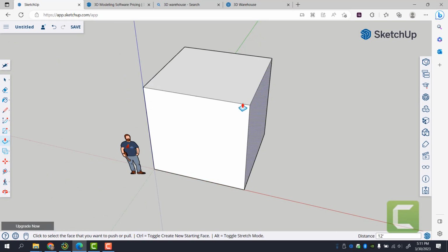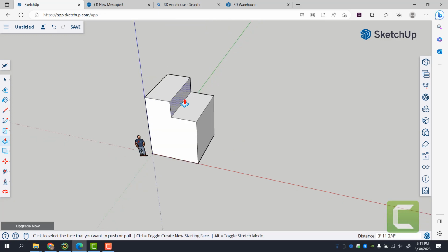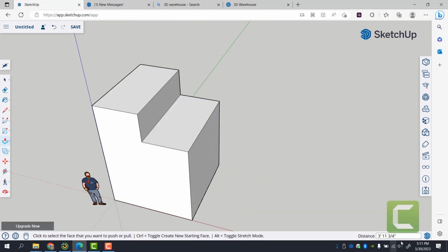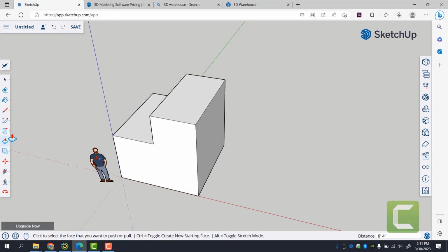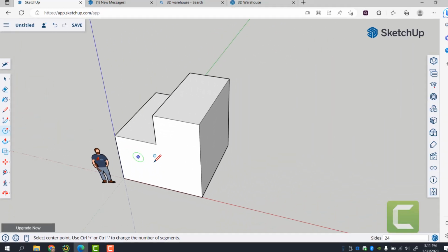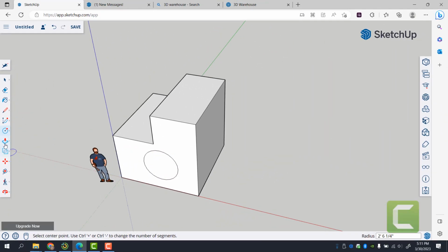side your mouse is on. Next, you're going to be looking at this line tool. So I'm going to use the line tool to divide this surface. Now, if I divide the surface, it becomes two individual surfaces, so they can be extruded independently of each other. Notice how it does that very quickly. Again, I can input the magnitude here, or I can subtract that difference in the 3D. Now, if I was to go ahead and draw additional shapes, again, it is very intuitive. You can go ahead and continue extruding.